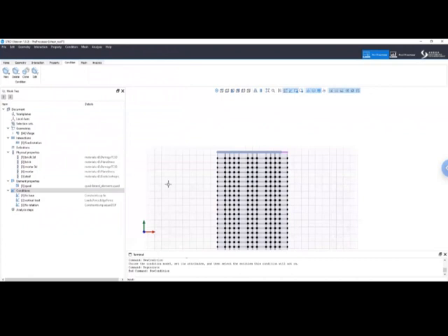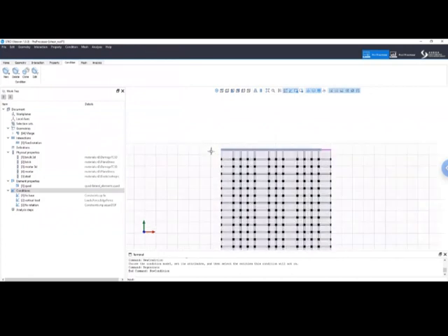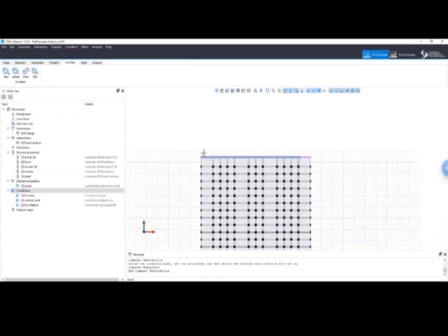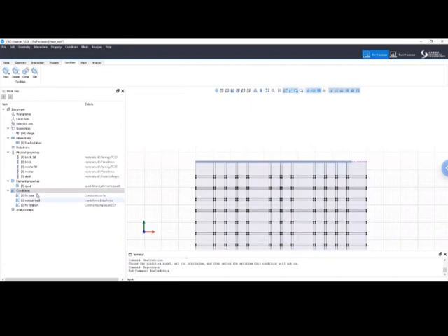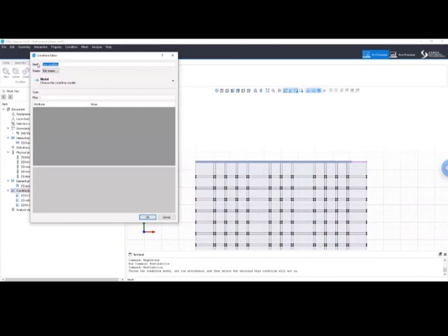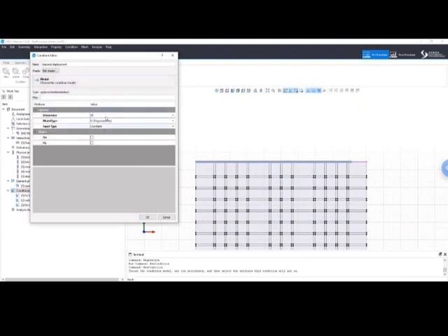Now the final boundary condition that we need is the imposed displacement. Now we can impose this displacement only to this point, because it's the master, so all the nodes will move by the same amount. So let's go under condition, add, and let's call it imposed displacement. An imposed displacement in OpenSees is actually a load. So we go under load, single point load, and we apply this one, which is the prescribed nodal value. We are in 2D, only displacement, and we want to apply a displacement.